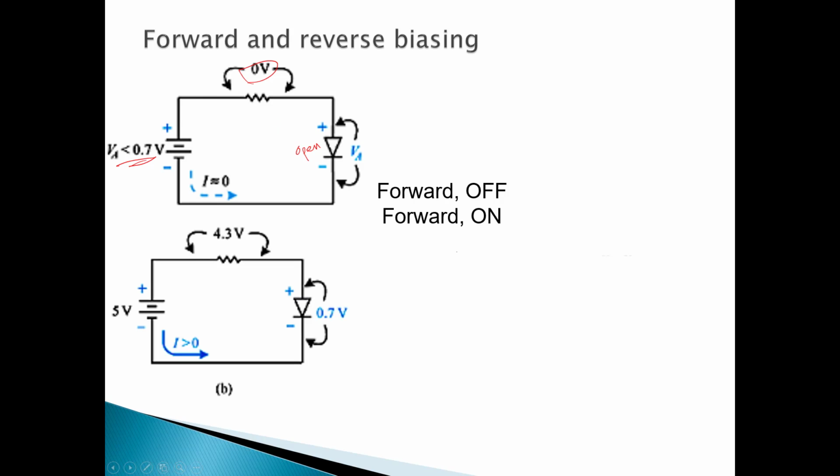Now, if I turn the voltage up a little bit further, which I've done here at 5 volts, this gets more positive than 7/10 of a volt. And so the 7/10 of a volt appears at it. Now the voltage here doesn't keep growing. Remember the curve, the one I drew so badly several times: once the diode turns on, it's on. And we don't think of it as having a voltage drop other than 7/10.